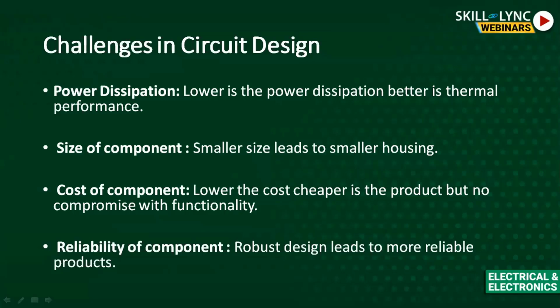One of the key parameters posing a big challenge in today's hardware industry is power dissipation. As you know, all the switching components generate heat inside the product, and every component has its own temperature limitations. Beyond that, if you try to operate it, you will damage the component, and in the end it will damage the product. That means the product will not work as expected. So this is really important. When you're integrating the components, you need to have a good focus on the thermal behavior of the product.